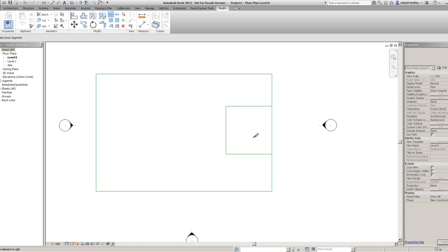Okay, back to where we were. So I've gone split element. Now I'm going to move my mouse away. First thing you'll notice is that my cursor is basically a little scalpel. Nice touch. And what I'm going to do, I'm going to hover over the object or element, or line in this case, that I want to split, and I'm just going to left click in the middle there. Hit modify, let's see what's going on.